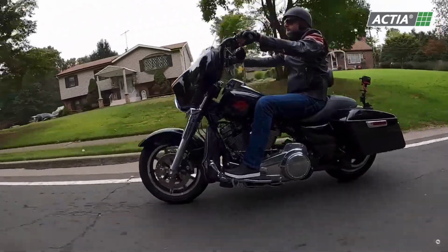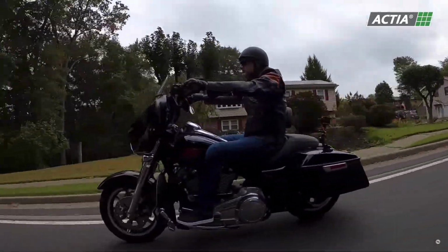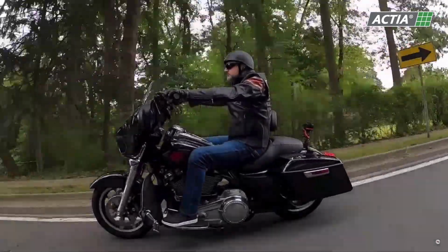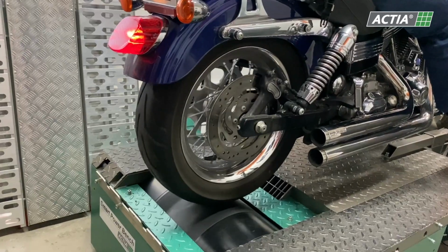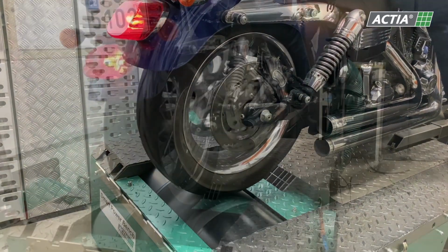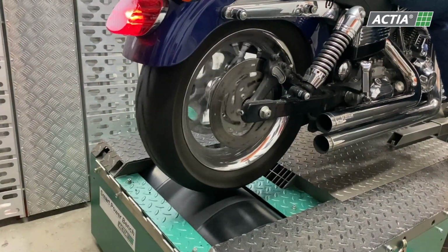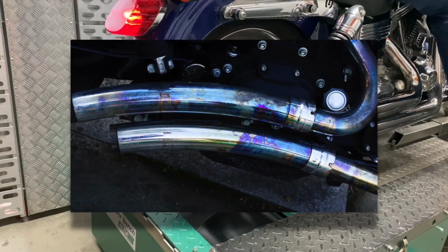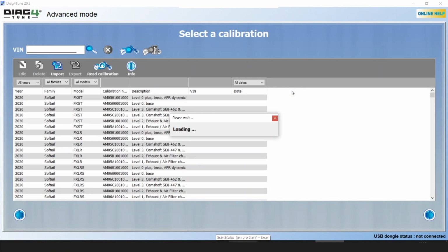The EFI control unit is still creating a fuel mixture for a standard engine without modifications. That means the engine often works with a lean mixture, and the extra air that the engine takes in isn't made use of at all. The lean mixture the engine ends up working with is then the cause for the majority of the negatives mentioned earlier: unstable performance, overheating, afterfires, decreased driving comfort, etc. That is where tuning with DIAG for Bike comes in.